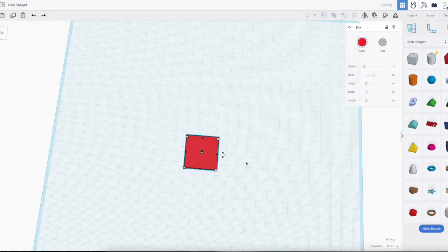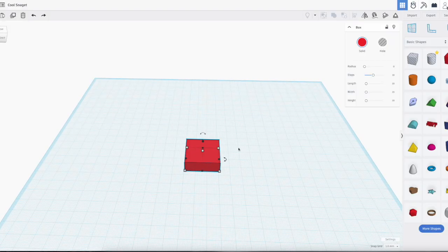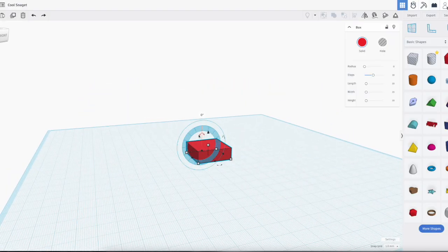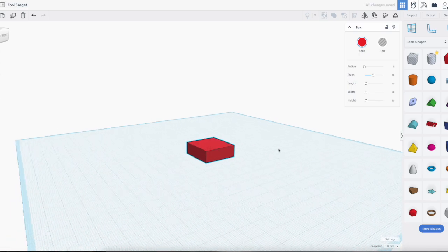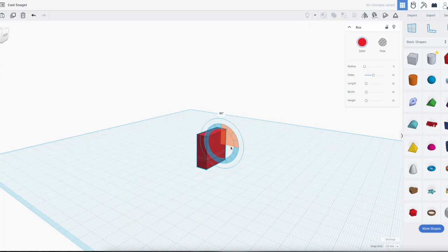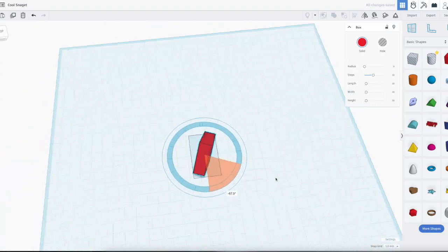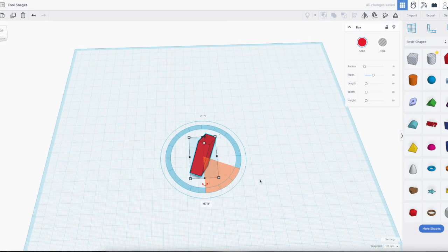I'm going to undo that. Again, undo is Command Z or right up here on your toolbar, the undo. If I rotate my view, you'll notice I have a left and right arrow, which will rotate it this direction. I also have, if I go over here, a left and right arrow. So I can rotate this in a lot of different ways. In fact, I can rotate it in 3 different ways, all 3 planes. Okay, so there is a rotate.